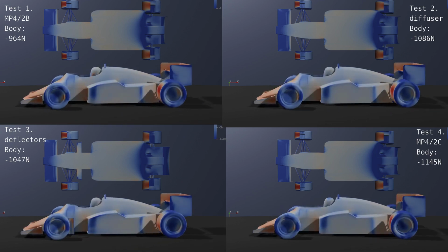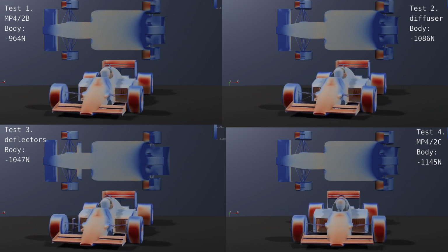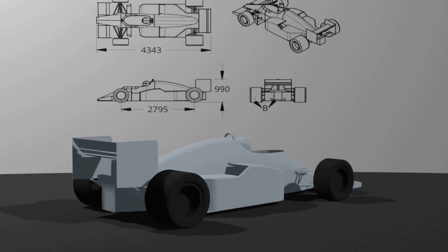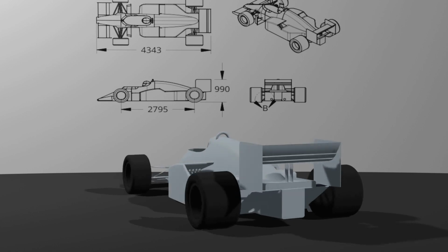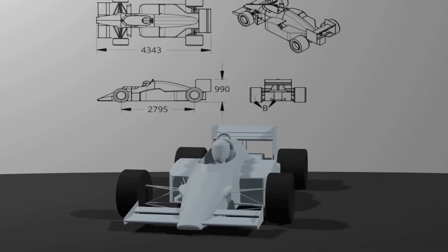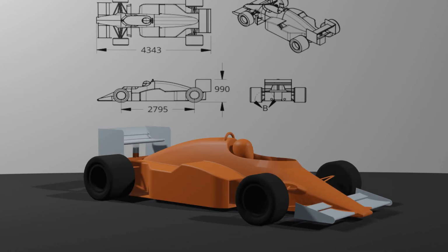Now to the experiment. All the parameters are the same. Essentially, once a case has been set up in OpenFOAM and works well, it is just a matter of rerunning with minor changes to the wheel speed and axle positions. All the parameters from now on will be added to the description. Outputs from the front wing, rear wing, body, and total summation of the forces will make up the table of results.